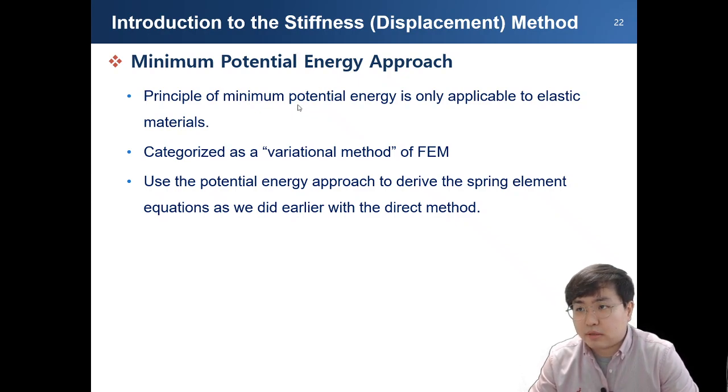It is because the potential energy means that when we apply some external force to the solid structure, this solid structure will be deformed. A deformed solid structure can always store elastic energy. Actually, when a solid structure is deformed inelastically, it can also store some internal energy. However, internal energy and elastic energy are slightly different.